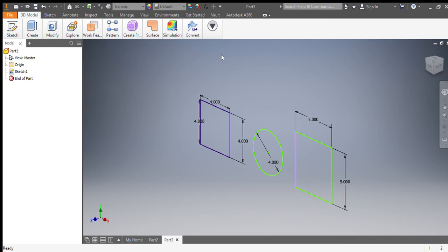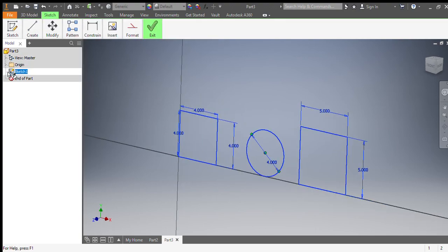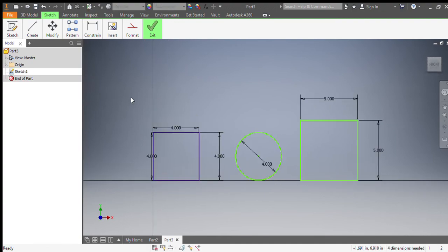So, right now, I want to show you one more thing because this happens all the time. So, if I am in sketch mode, okay, it's the end of the day, the 5-minute bell just rang, and I go File, Save. This error pops up, and I don't know if you can see it in the video, but it says you cannot save part 3 in sketch mode. Would you like to exit sketch mode and continue saving?